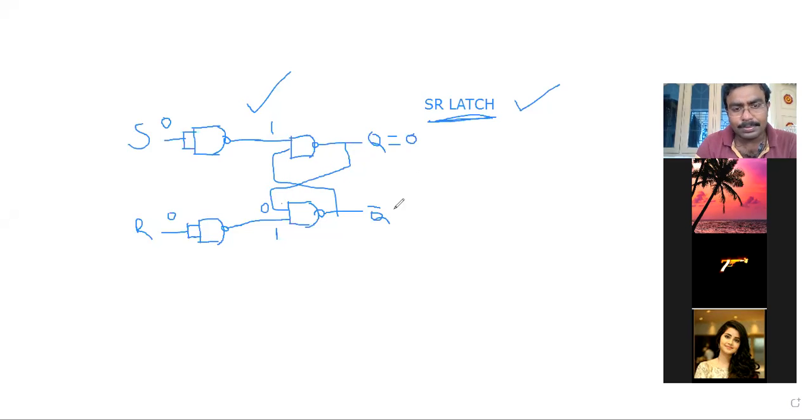Guys, remember one thing. If you are having 0 and 1 as inputs to the NAND gate, what output will you get? 1, sir. 0 into 1 is actually 0 when it is a multiplication, and the inversion of that is 1. So I'm going to get 1, guys. So at this lead, you are having 1, and through this line, this 1 will reach this point.